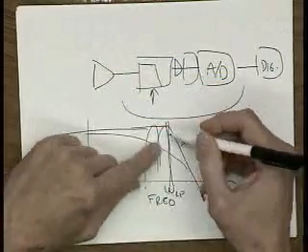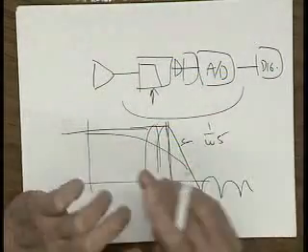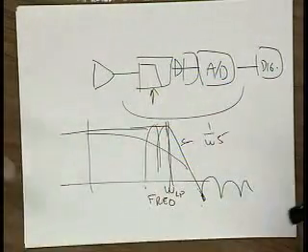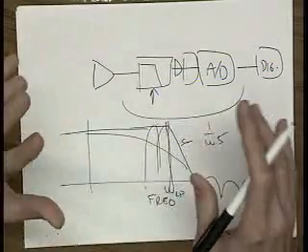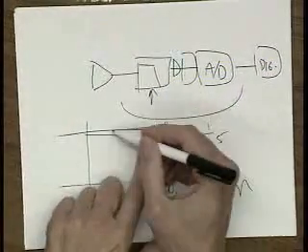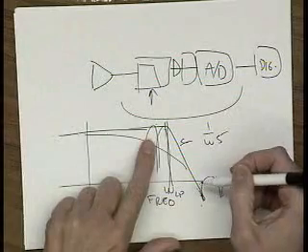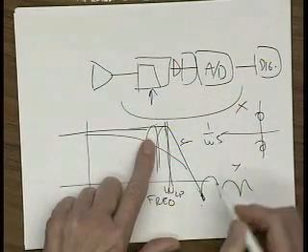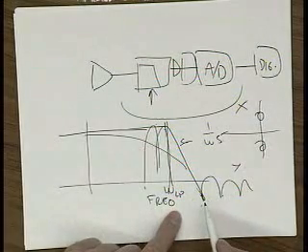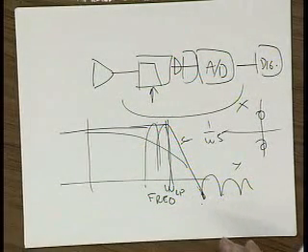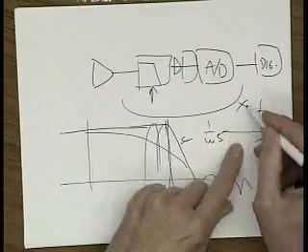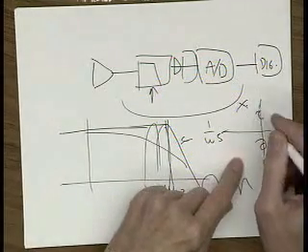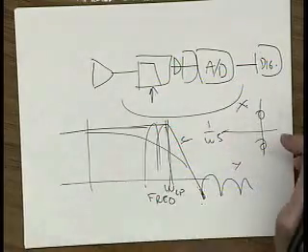So there's a filter design problem associated with poles and zeros. Well-solved problem. There's programs that do this. MATLAB has good programs that do this. You can give about any filter spec. It'll pop back with the poles and zero locations that would give that filter response spec. Okay? So now, our job is, how do we design circuits that create these poles and zeros at arbitrary location?